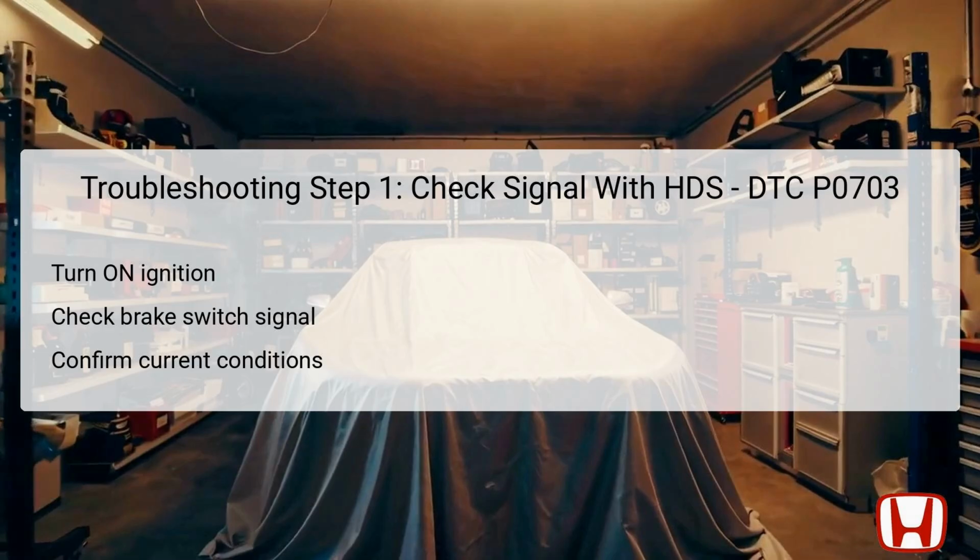This allows you to view the switch's current conditions and see if they match the expected threshold values. If the conditions do match, you can move forward in the troubleshooting process to Step 7. Conversely, if the conditions do not match, you will need to proceed to Step 2 to further investigate the installation of the brake pedal position switch.